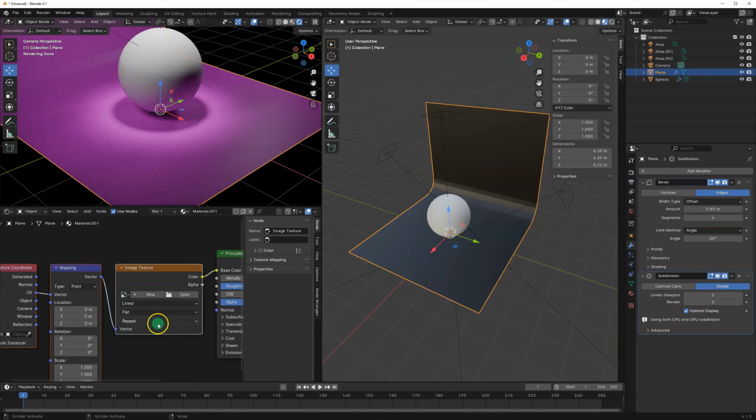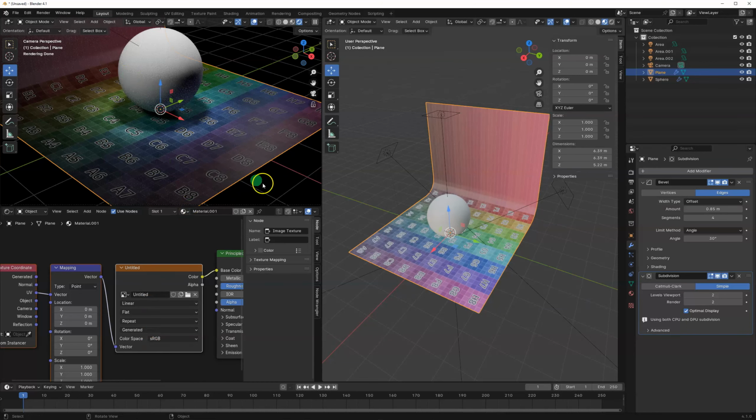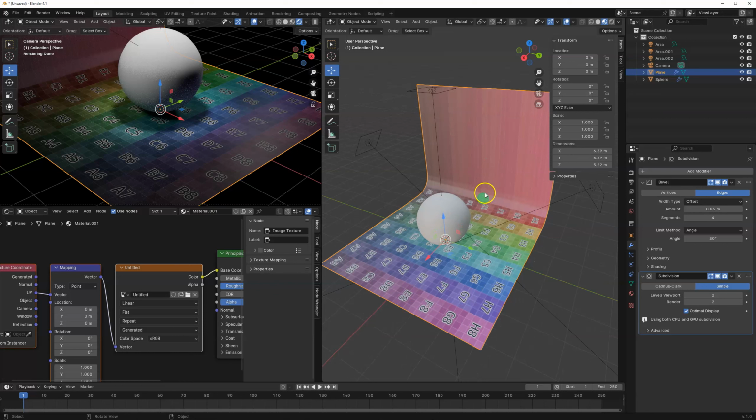And if we click new, and instead of blank, add a color grid and go new image, you'll see a color grid appears in the rendering. And you'll note that the color grid has been stretched right up here. Now that's because we don't have any UVs set out properly. This typically will happen to a CAD model if you bring it into something.